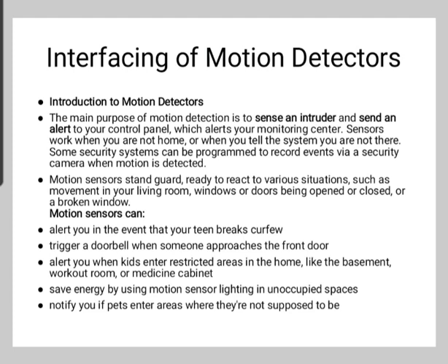One potential drawback of the ultrasonic sensor is that it can be sensitive to motion in areas where the coverage is undesired, for instance due to the reflection of sound waves around a corner. Such extended coverage may be desirable for lighting control, where the goal is the detection of any occupancy in an area, but for opening an automatic door, for example, a sensor selective to traffic in the path towards the door is superior.